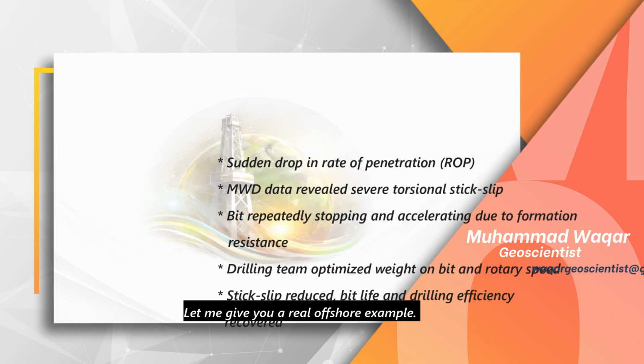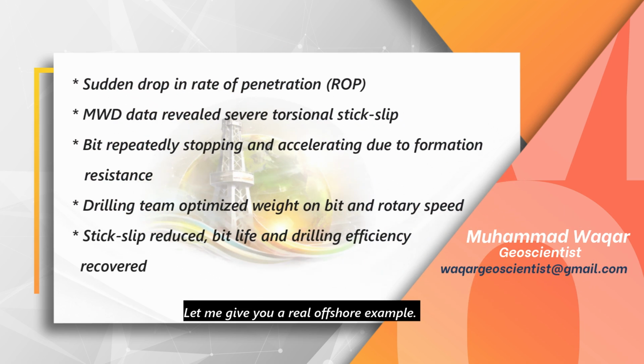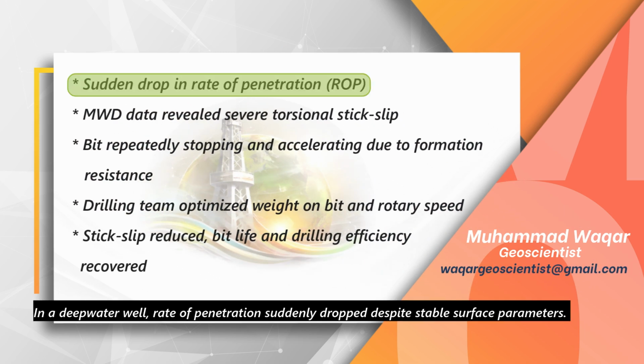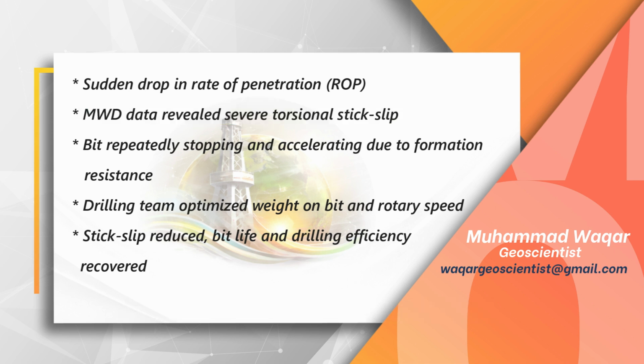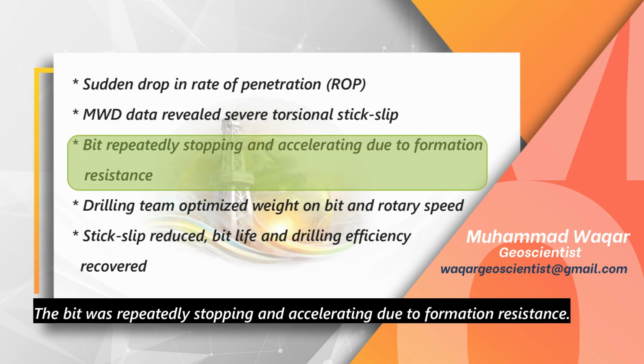Let me give you a real offshore example. In a deep water well, rate of penetration suddenly dropped despite stable surface parameters. MWD vibration data showed severe torsional stick slip behavior. The bit was repeatedly stopping and accelerating due to formation resistance.